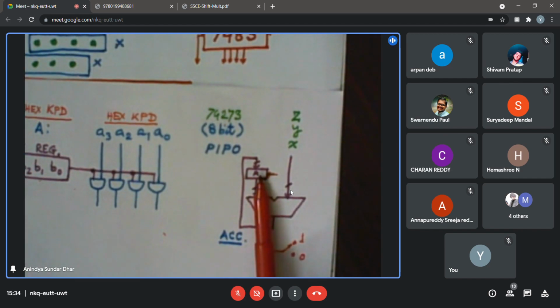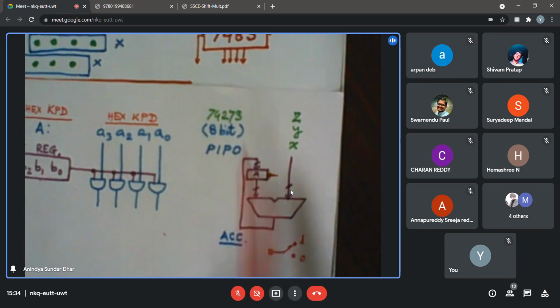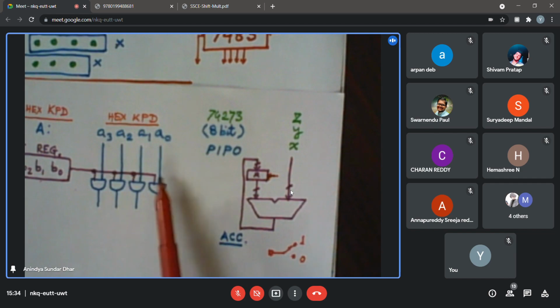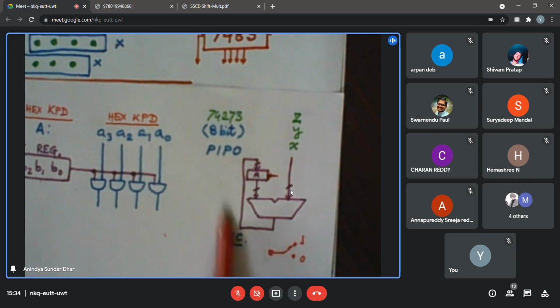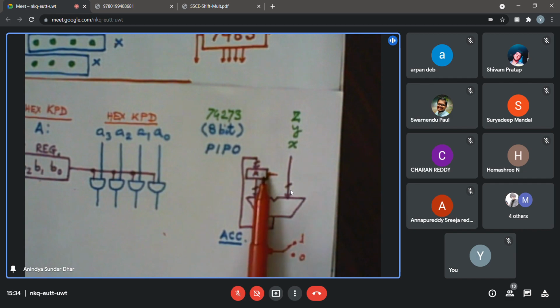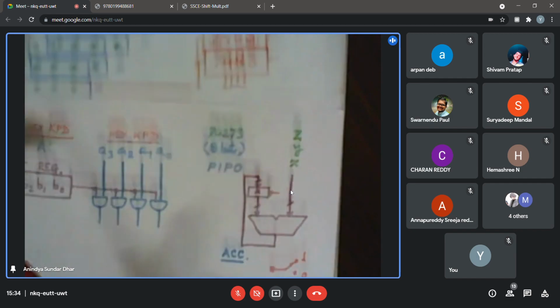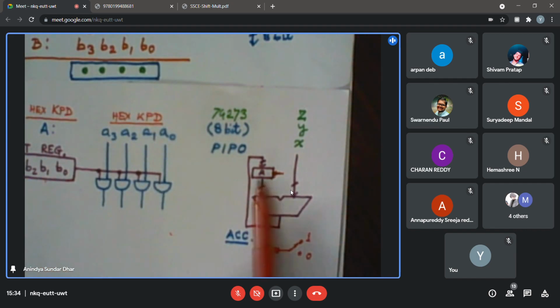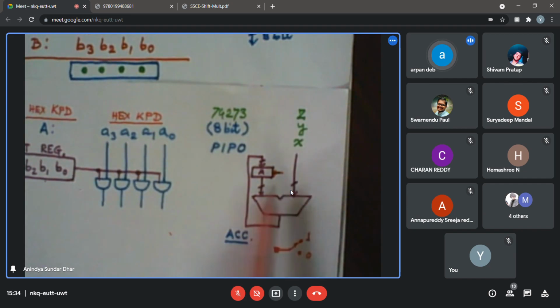If I put a register, which is an 8-bit 74273, along with some sort of adder, it might be a little tricky. If I connect it as one of the inputs to the adder, the other input is coming from maybe this partial product part, where we are generating those things, and then we are gradually accumulating that. So maybe initially after resetting it to 0, we first add this 4-bit. The initial value of the register is 0, and now I am sending this partial product. Okay, so then what will happen?